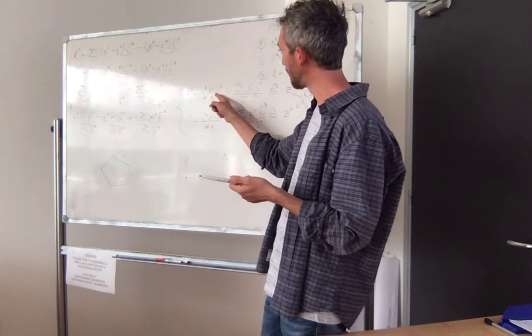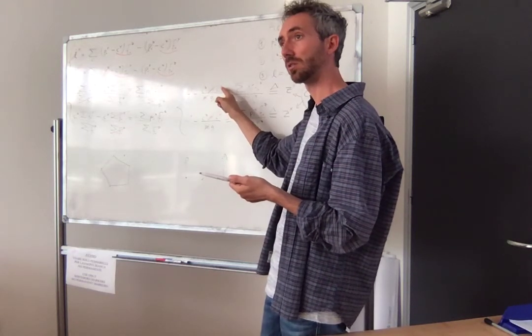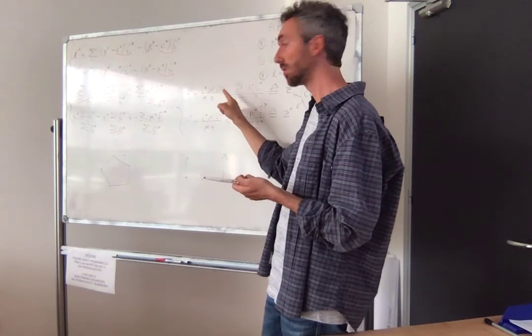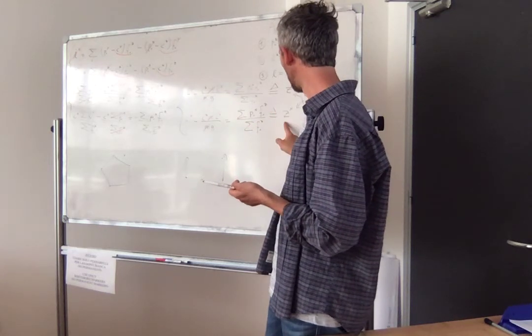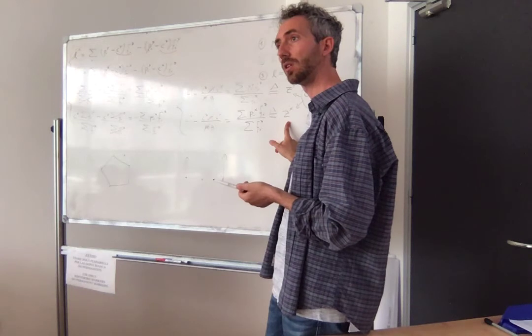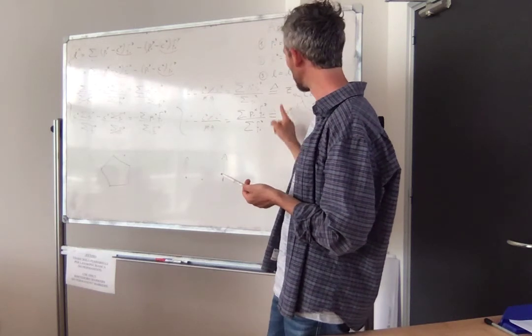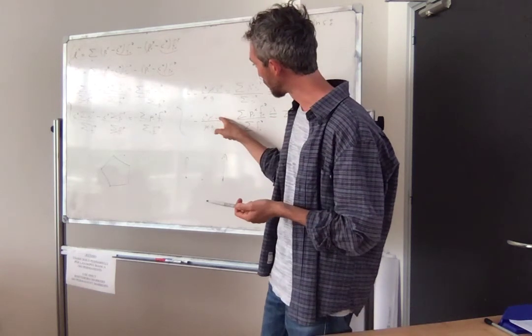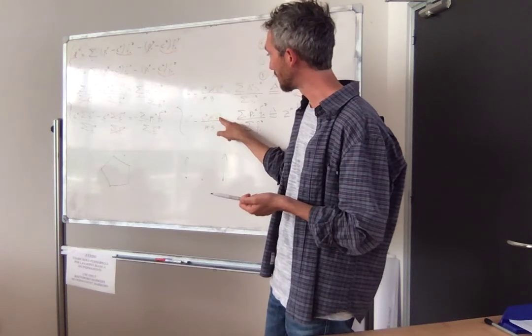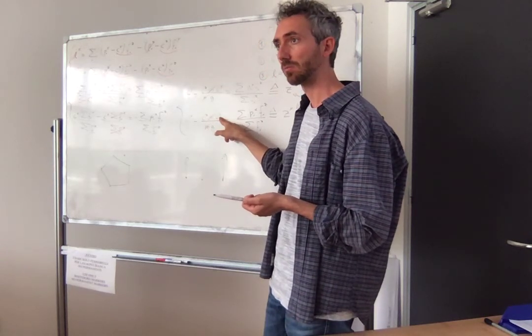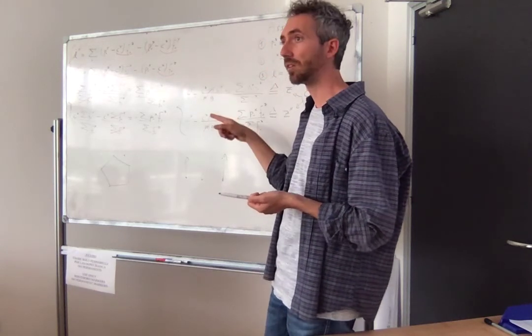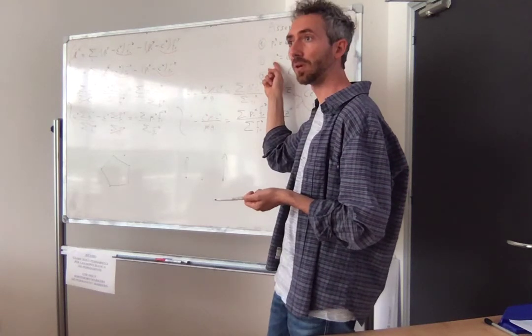That is what defines my center of mass acceleration. Okay, so my new control variable is going to be the center of pressure, and by choosing the center of pressure, I can compute directly the center of mass acceleration in x and y direction. In Z, it's 0 by assumption.